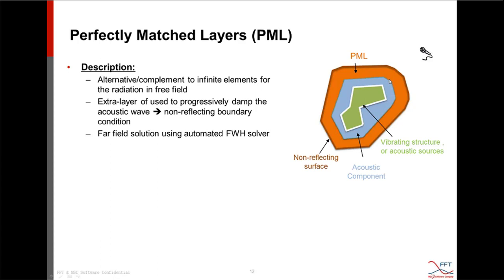And then we are adding an extra layer, that is the PML layer, that damps progressively the acoustic wave through its thickness. And far field result is solved using a Ffowcs Williams-Hawkings solver, or FWH solver, in the PML model.